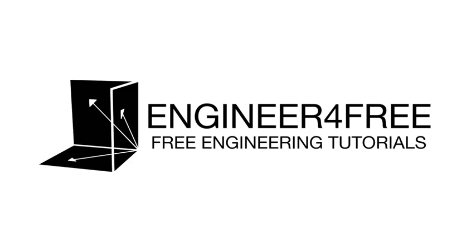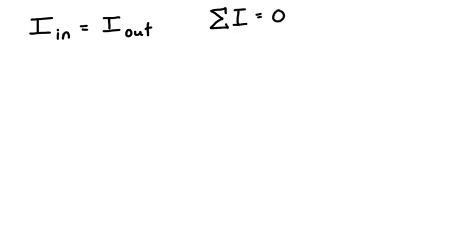So Kirchhoff's current law states that the algebraic sum of all currents entering and exiting a node or a wire junction is 0. So that means that just algebraically, the current flowing in is going to be equal to the current flowing out of a junction. Or we can also state that as the algebraic sum of all currents at a point is going to be equal to 0.